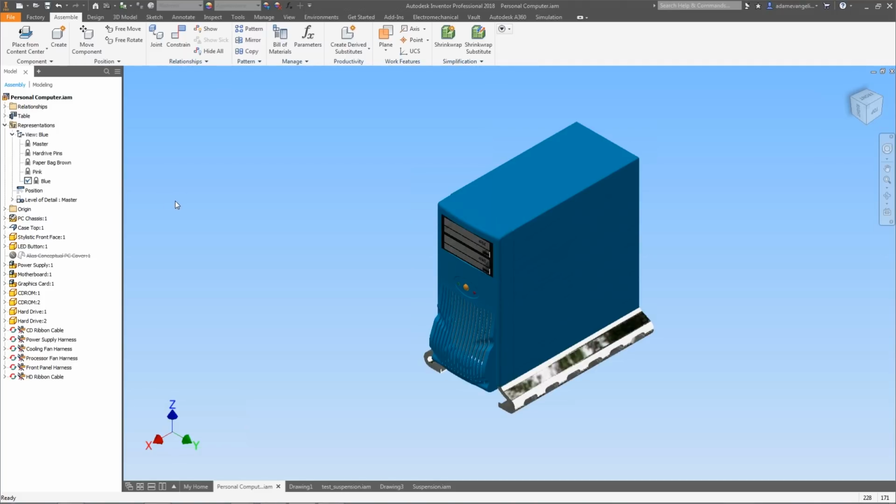Locking those views locks that particular state in that particular moment in time. So sometimes you want to default back to that, which is the case in which you would lock it. There's definitely cases where you want to lock them. There's certain cases where you also don't want to lock them. So if you're making a lot of edits and you want to make those happen all of the time, then leave it unlocked. But once you're done with your assembly, your whole setup, you've got your view as you want it, and then you want to get to that point where you're going to port over to that IDW file or that DWG file for those who create DWGs in Inventor, go ahead and lock it, especially if you don't want to change it in the future. Yeah, no, definitely, yeah. So you can kind of think of these locked states as kind of fallbacks.